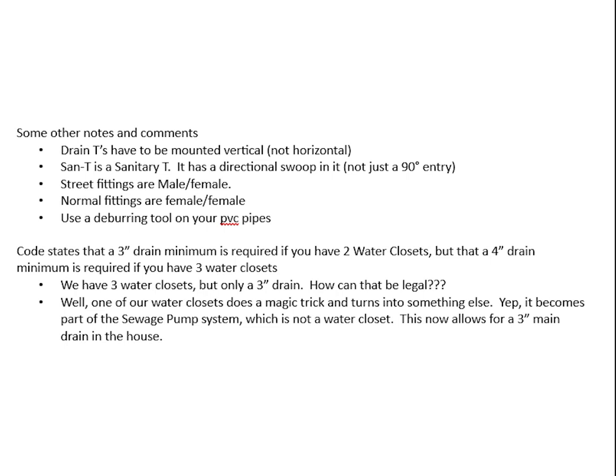Code states that a 3-inch drain minimum is required if you have 2 water closets, but that a 4-inch drain minimum is required if you have 3 water closets. Well, we have 3 water closets, but only a 3-inch drain. How can that be legal? As mentioned above, one of our water closets does a magic trick, turns into something else. Yep, it becomes part of the sewage pump system, which is not a water closet. This now allows for a 3-inch main drain in the house.